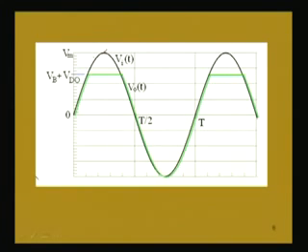So, this is a typical example of a constant voltage drop model considered for the diode, and this is a simple clipping circuit, which clips a portion of the waveform, the upper portion is clipped. So, we can design different clipper circuits according to our need.